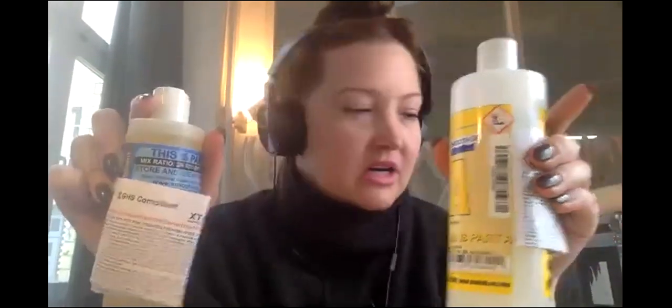Okay, so this stuff is super easy. I like to do it by weight, it's even easier. But basically, you mix this 2-to-1 by volume. You can buy these kits. They come in bigger kits as well. I think that's the smallest one, and it comes with this little measuring cup. I, however, prefer to just do it by weight, which I also wrote in the notes in this slide. And so basically, I just have a little plastic container and I measure out the correct proportions.